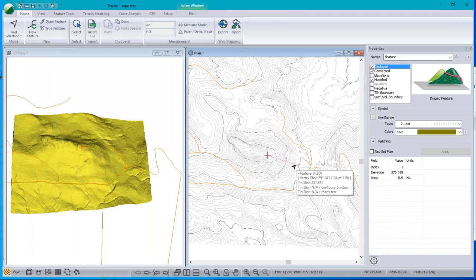The other possibility, which happens in the tropics, is that the material simply doesn't support fill. It has poor integrity. It's full of clay, or I don't know. Anyway, often in the tropics, you can cut a full bench road, but you cannot build a road on fill. So even though the side hill may not be so steep, they still use full bench.